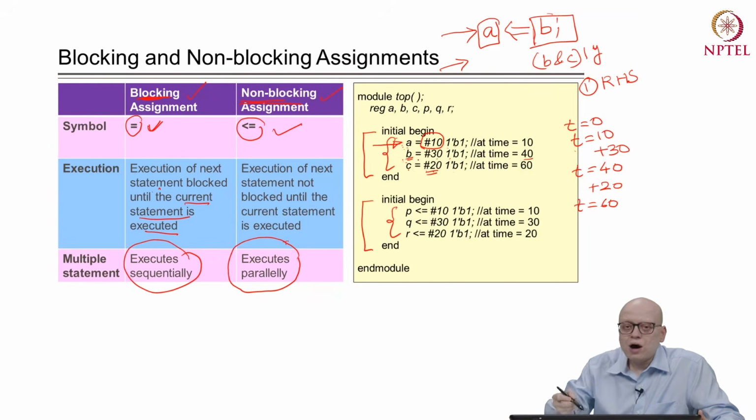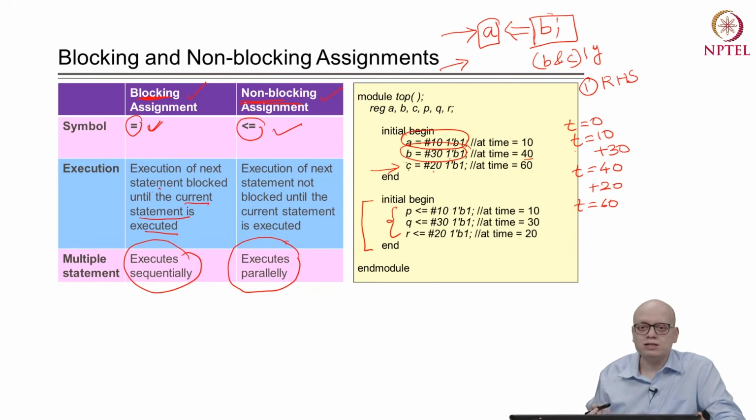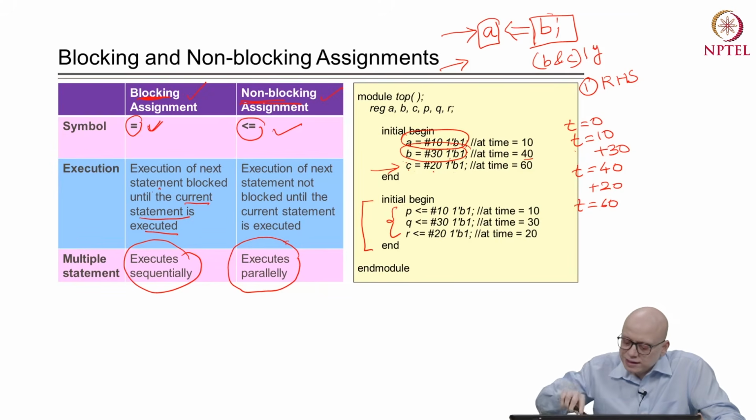So, this assignment has happened in a blocking manner, meaning that the execution does not reach the next statement until the first one has done all the processing. Similarly, it does not reach the third statement until the second one has also done the process, right. So, this is a kind of blocking assignment similar to traditional programming languages, nothing different, right. But something interesting happens in